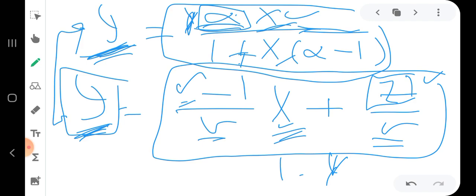And the other case is where the relative volatility is not given. Keep in mind that the first equation is obtained from the equilibrium relation, and the second equation is obtained from material balance. The equation obtained from material balance does not contain the relative volatility, so it will not change.